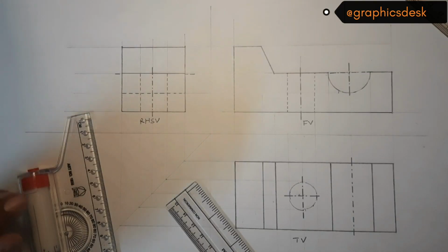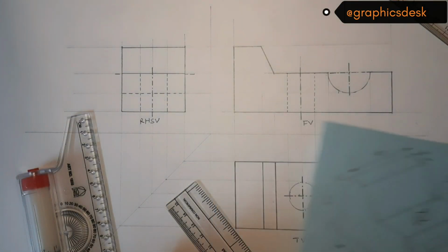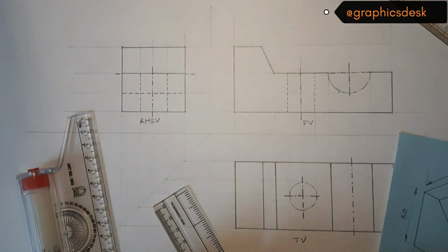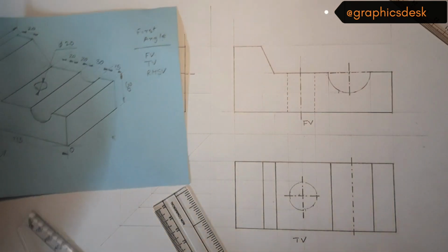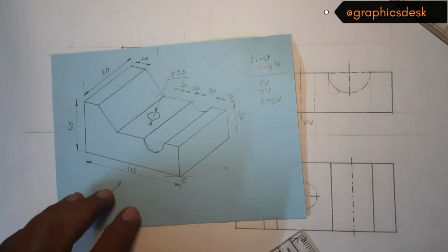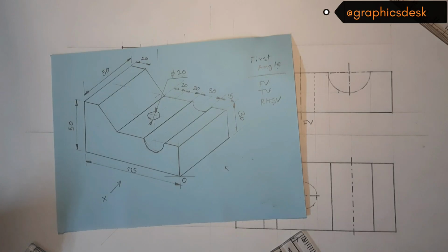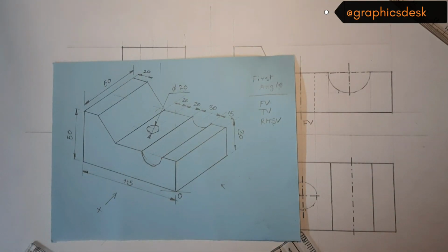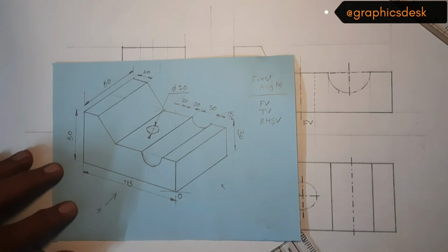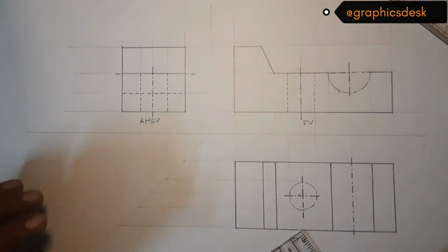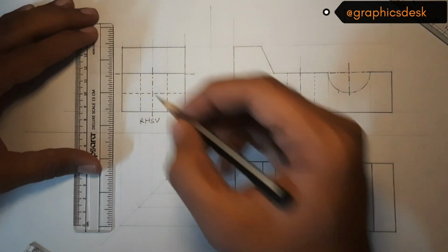So don't draw the center line from the top, which should be essentially like this only. Okay, now let's take a minute to all the dimensions, because our geometry is completed now. Let me give the dimensions of it. So all those dimensions which are mentioned in this diagram, in the problem statement, we have to make sure that all of them are basically given in any of the view. Now generally the thumb rule is that the maximum or more dimensions which are clearly visible in any of the view, those are to be drawn. So I'll quickly do the dimensioning of this diagram.